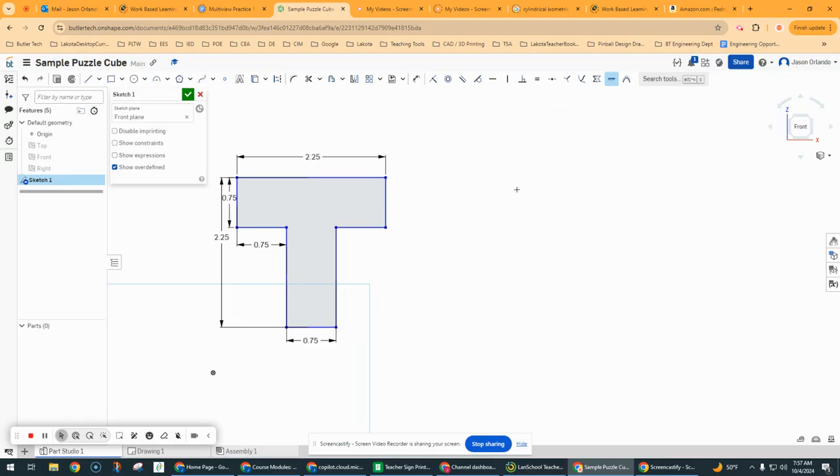And the only thing I generally would fix, usually, is a single point. Okay, so I'm going to fix a single corner. Having a system to how you do that, like always using the lower left corner or always upper right corner or something, would be helpful for you just to kind of find those fixed points later if they're ever causing you trouble. Fixing too many pieces of geometry is usually a bad thing.